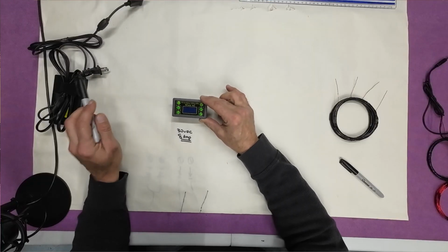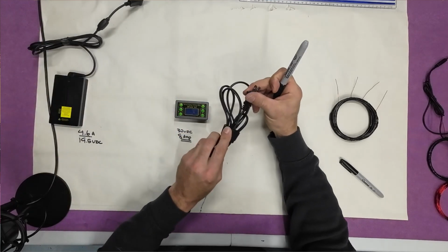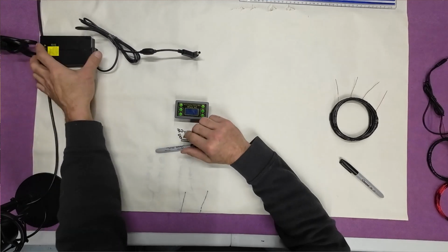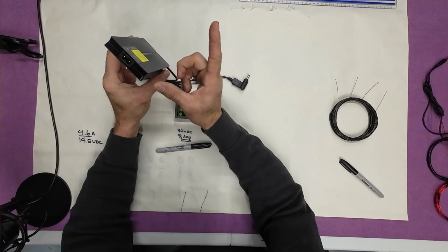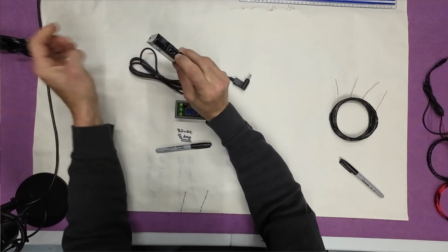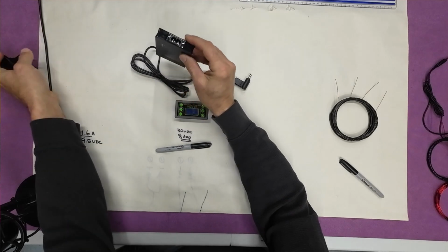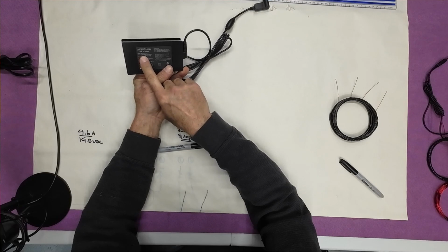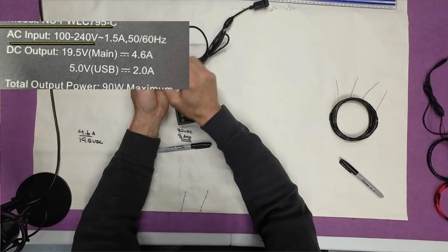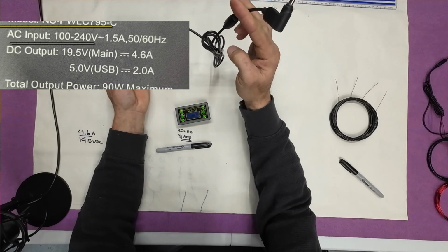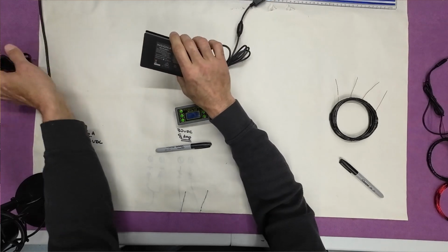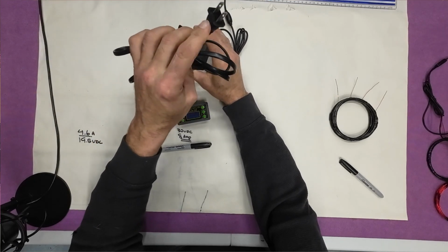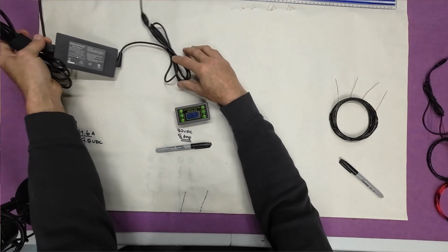Now, the way to wire this, well, you got your outlet power supply that comes in to your 120 volts. Oh, side bracket. These power supplies, the plug-in at the end, they change depending on the country. They're rated to be inputted with as low as 100 volts and as high as 240 volts. And no matter what, you'll have the same voltage coming out of the other end, okay? So it doesn't matter where in the world you live, a laptop power supply will work. You just need to match the cord end with that, okay?